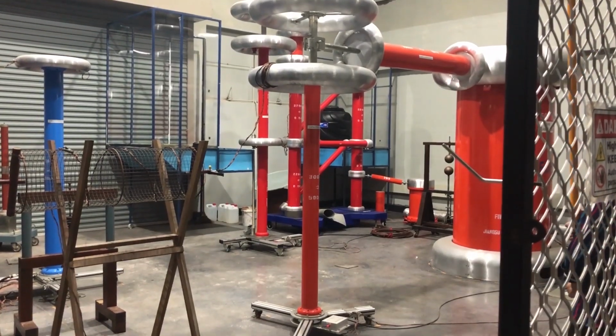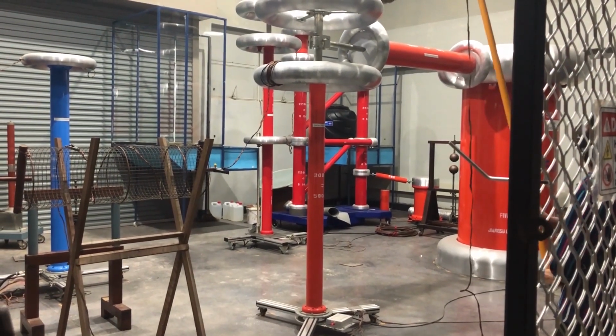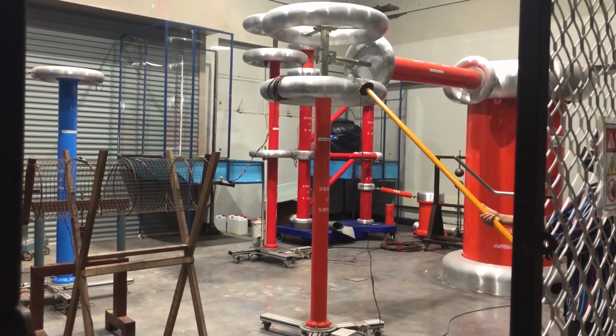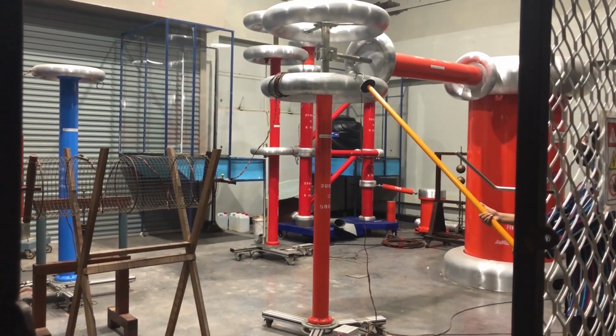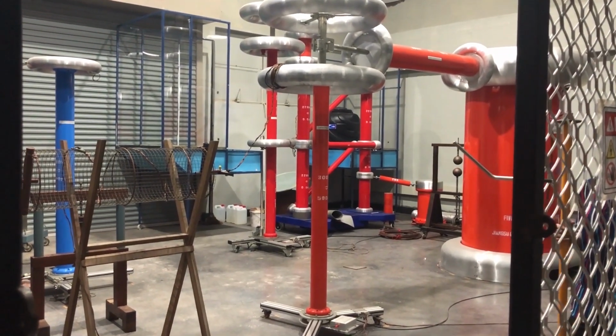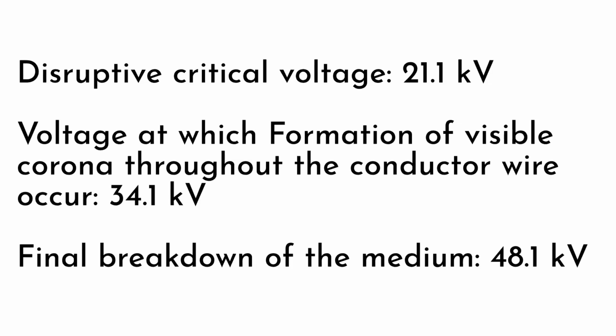After all these steps, we have to switch off AC sources from breakers and should discharge the capacitor as shown here. Use these observations when preparing your lab report.